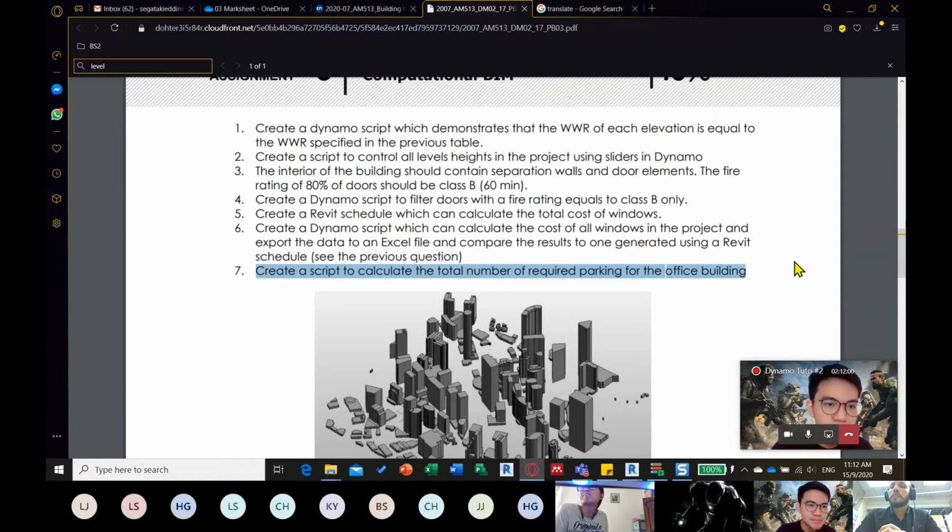So if I tell you we need 1 car parking per 46 square meters of floor area, this means if you can extract the office area and you know the requirement for 1 parking is 46 square meters, you can make a division, and you can even develop it as a Dynamo Player script, making it compatible with Dynamo Player.